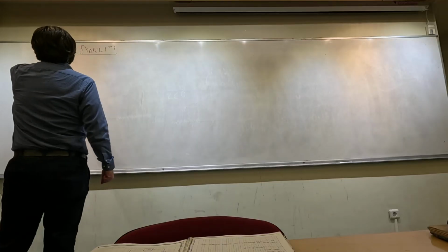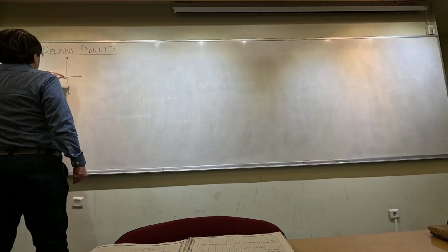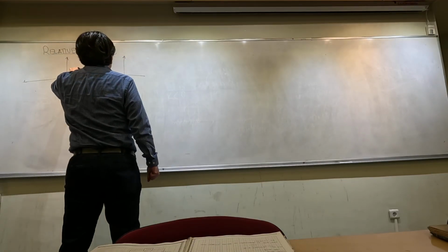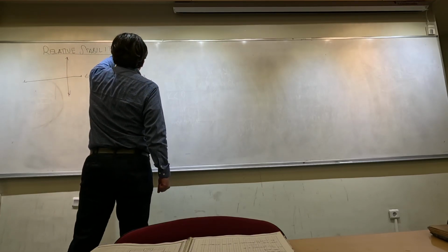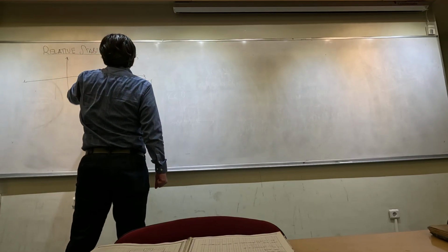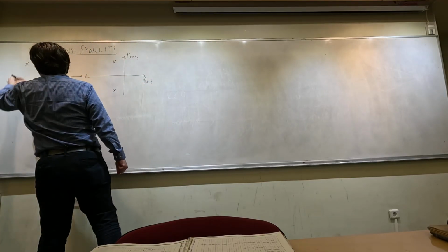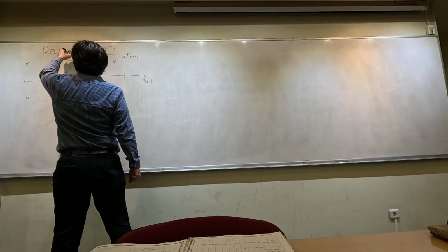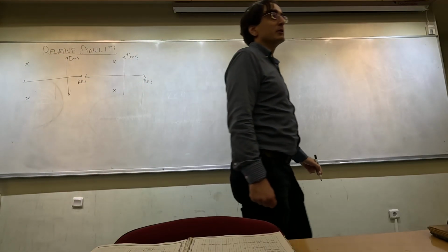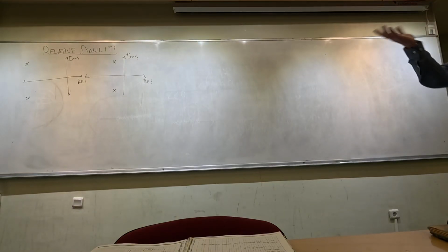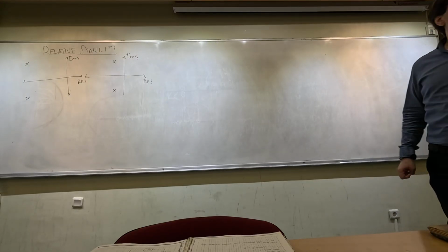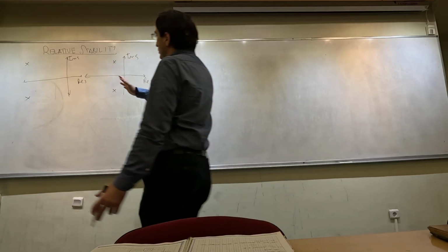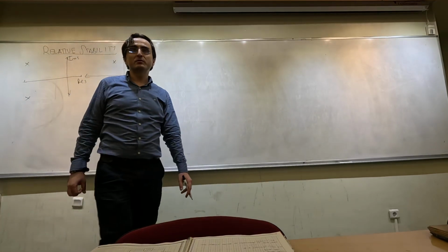So suppose that I have two stable systems. Okay? I have two stable systems with the following pole locations. I have for the second system these pole locations, and for the first system I have these closed loop pole locations. Which system do you think is more stable? Both of the systems are stable, but one of them is more stable. Which one is more stable? The left one is more stable. Why is that? Because it has its closed loop poles further away from the imaginary axis.